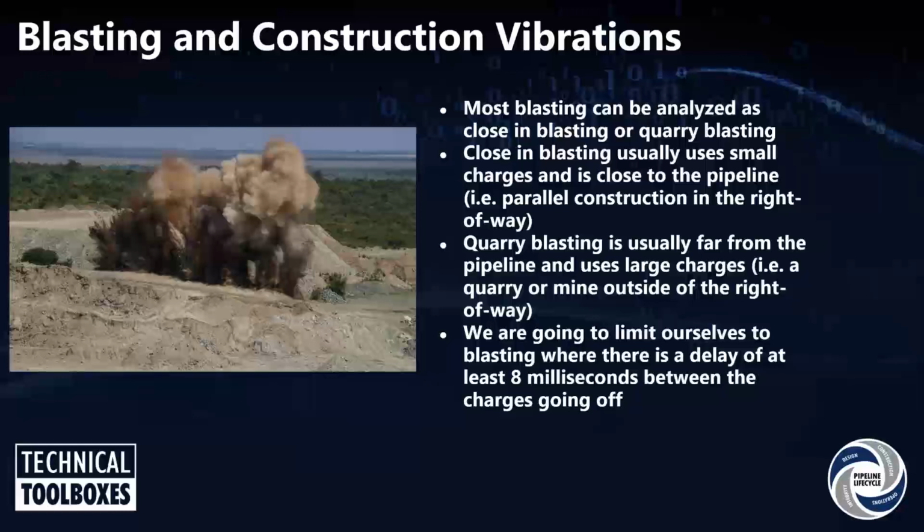That's when it's far away. On the other hand, if blasting is going to take place near the pipeline, for example, within the same right-of-way, or 30 feet or 40 feet away, we have a different set of equations and methods, which is based on Esparza's equations. And sometimes it may not be obvious.